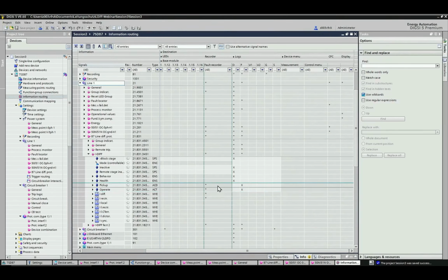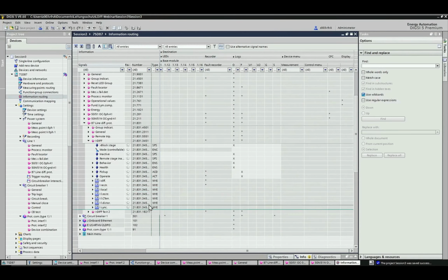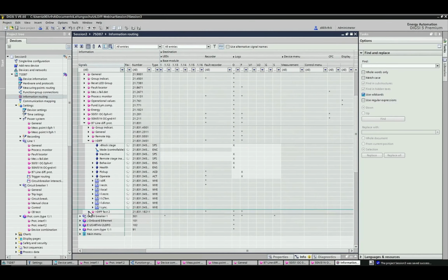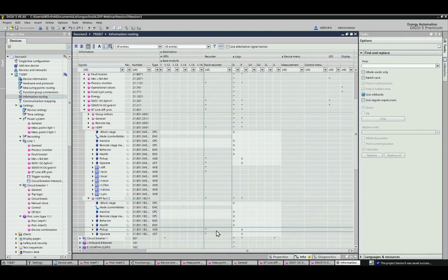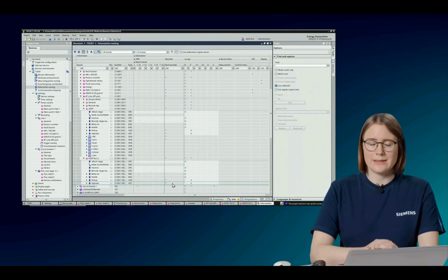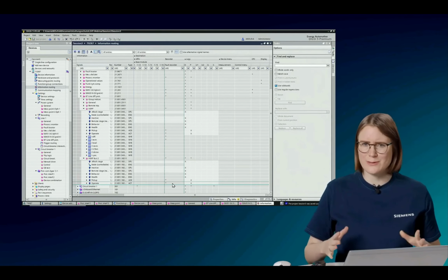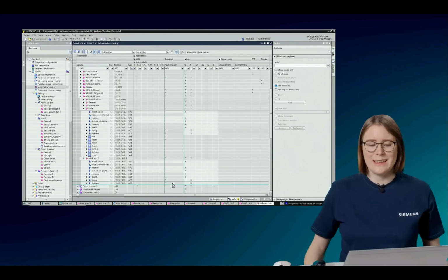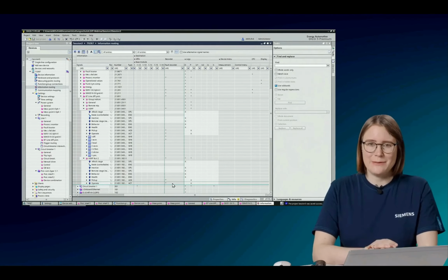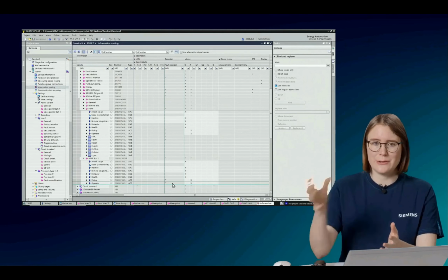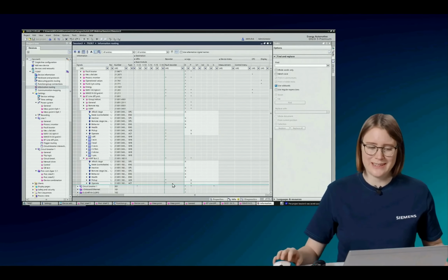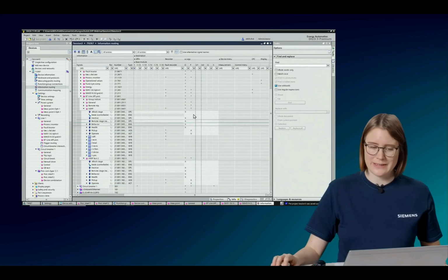Also, it makes sense to see pick up and operate for the IDIF and the IDIF fast 2 stage. You see at the moment that these signals are already assigned to the recorder, and this is a DIGSI feature since DIGSI version 9.60, that even if you insert the function newly from the library to the device, then these routings are done automatically.